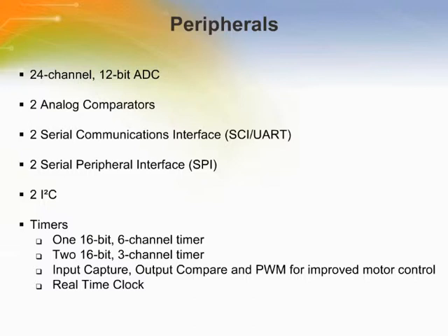The analog comparator provides a circuit for comparing 2 analog input voltages or for comparing 1 analog input voltage to an internal reference voltage. The SCIs offer asynchronous communications, 13-bit break option, flexible baud rate generation, double buffered transmit and receive, and optional hardware parity checking and generation.